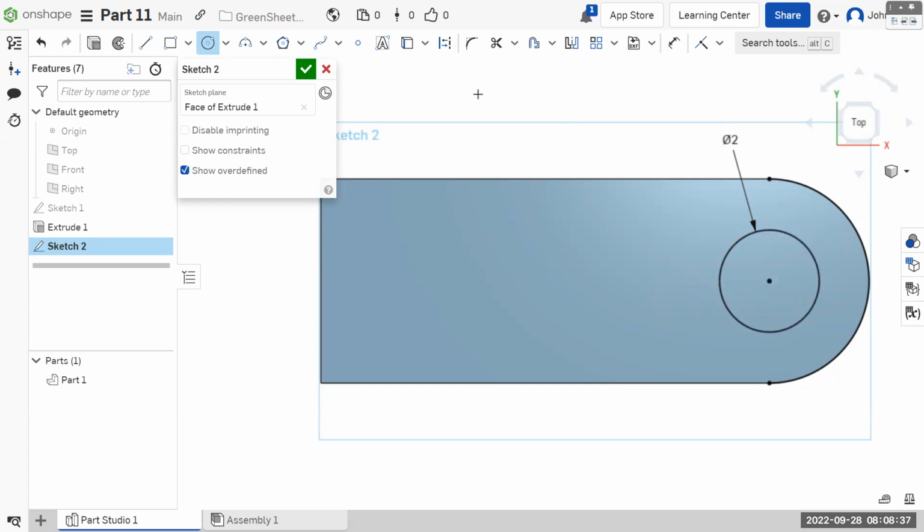All right, so this is a little trickier, and I can show you a more foolproof method. But so I want a circle that lines up exactly horizontally with the center of this circle, but it's not giving me any sort of snap. If I mouse over without clicking the center point here and travel out this way, you can see I get like a soft snap there, which is what that dotted line would be. And so I can from there make another 2-inch circle. Dimension this to 2.